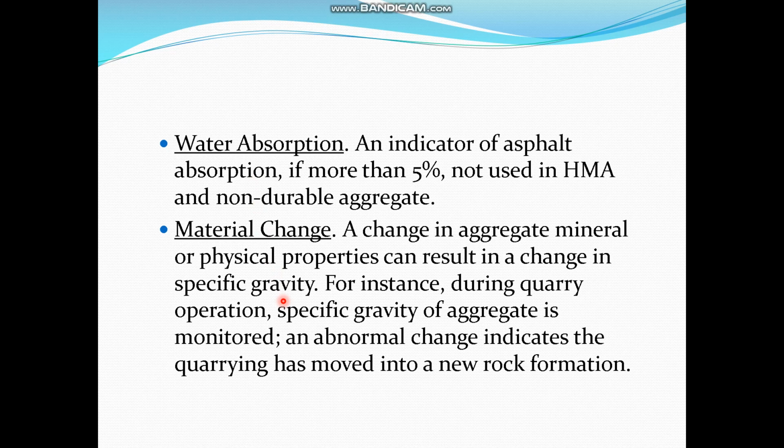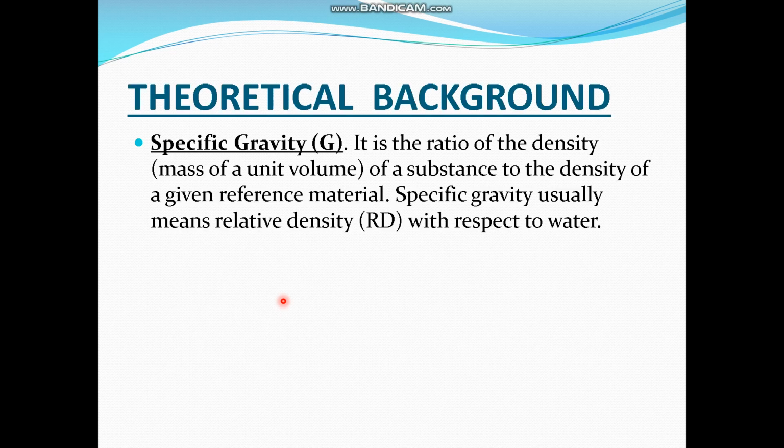The water absorption is also determined as a measure of the void percentage. Again, if we have to see the quality of your aggregate, this is another check which we use to determine whether your aggregate source is the same or not, because usually the aggregate used in Islamabad is from the Margalla hills. So the specific gravity of your source, that is from which hill you acquire the aggregate, will remain the same, and that is another way of determining the source of your aggregate, that is from where you have acquired it.